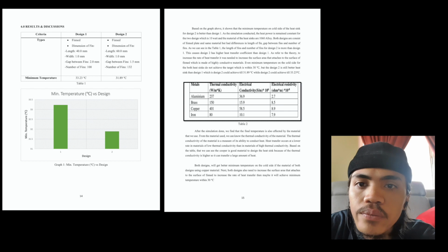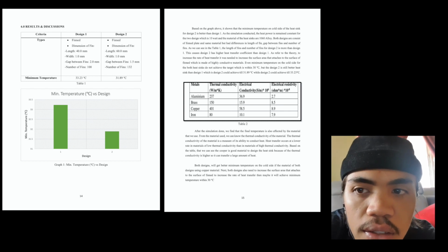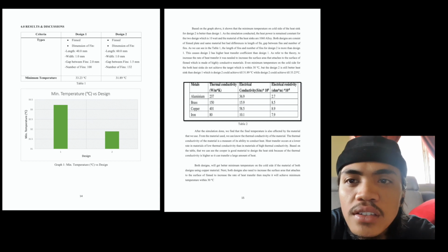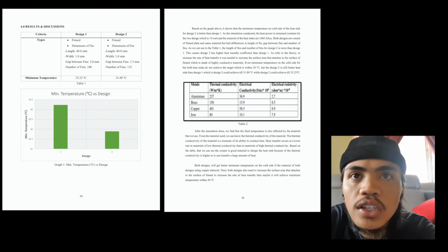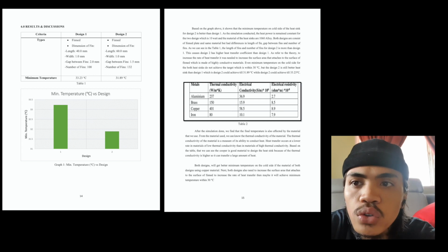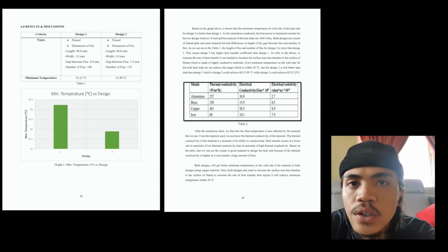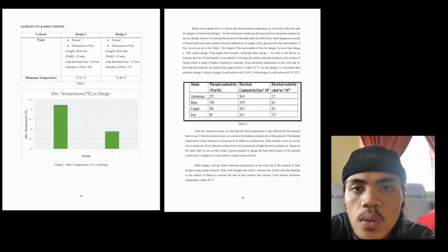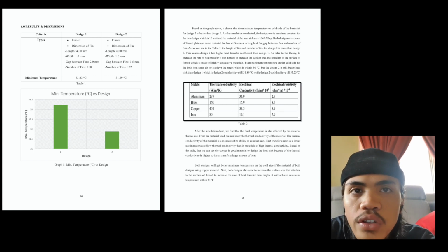Okay. Actually, lastly, the best suggestion for a heat sink is using copper, but aluminium is the most common material for heat sinks. Why do we always use aluminium? Because aluminium fits the needs of most projects around the world, and this metal is lightweight and has relatively good thermal conductivity.